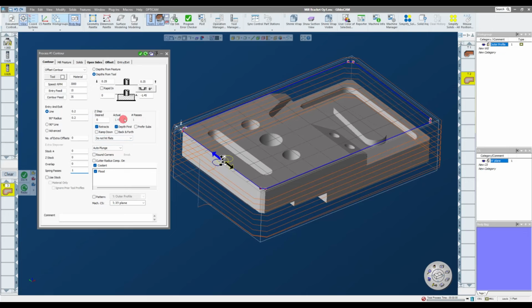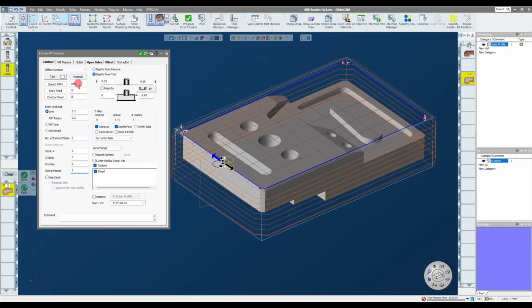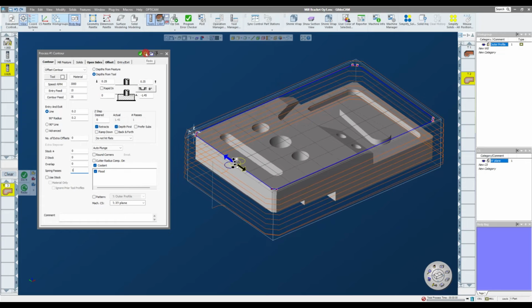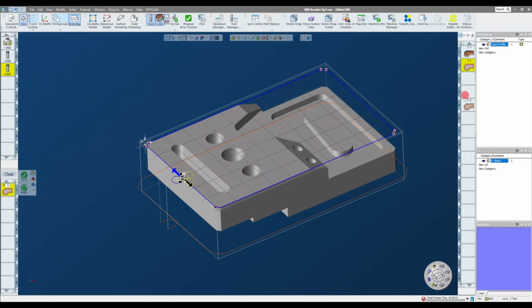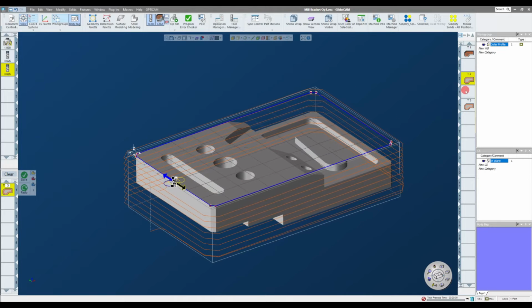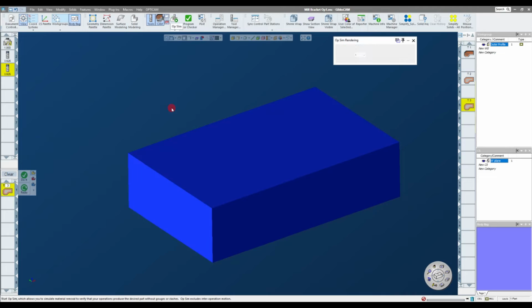My markers are already set, my depth is already set, my cutting parameters I slightly modified, my lead in and lead out is there. Instead of doing redo, which would change my roughing operation, I would simply click do it. And it now creates a finish operation right below my other one. So you can take these operations, you can move them around, you can put spaces in between them. Sometimes if I'm using different tools, I'll keep an empty space in between separate tool operations. Totally up to you. So now that I have that, I can go into my OpSim.